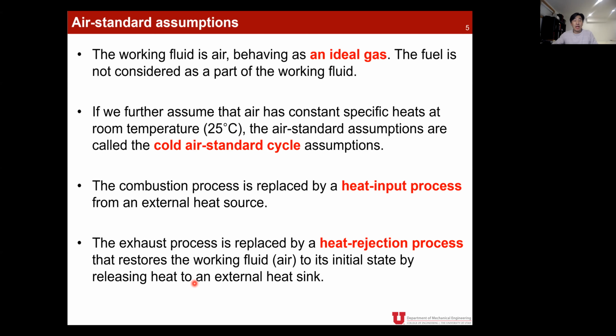Now, another feature of the air standard assumption is that we don't worry about the combustion process because we already excluded the fuel. The combustion process is replaced by a simple heat input process. We just assume that a certain amount of heat is transferred into your engine during this process. So that makes our analysis a lot easier.